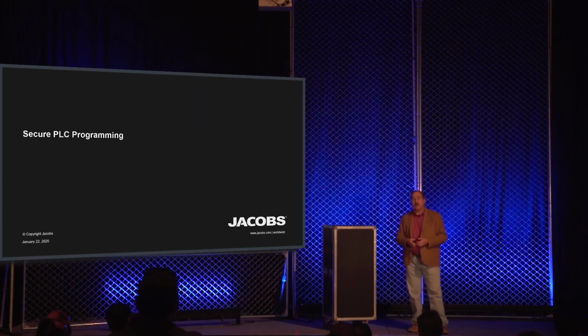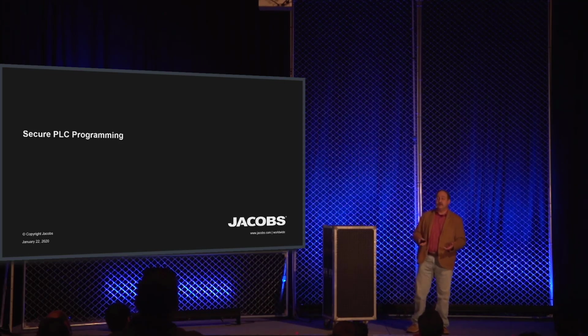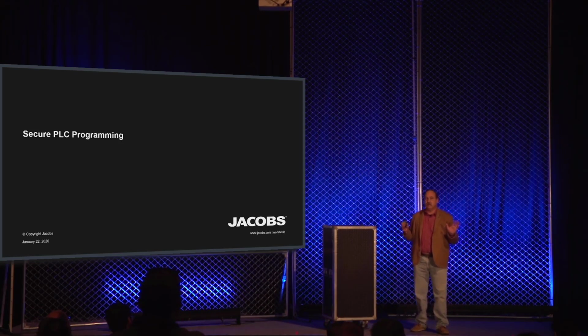So when you say, can we validate the code? Well, the code isn't always the problem. It's the I/O. And you get to that I/O and you make lots of tests. That's another thing you can do: you should make the PLC able to divorce the logic from the I/O so that you can do I/O testing. So you can see exactly what it does when you do it. And use a graphing function within the PLC sometimes. It's gathering the data at a fairly high resolution, so you can actually see what's going on. And it's best to do things at the lowest level possible. Always push these functions as close to the field as you can.